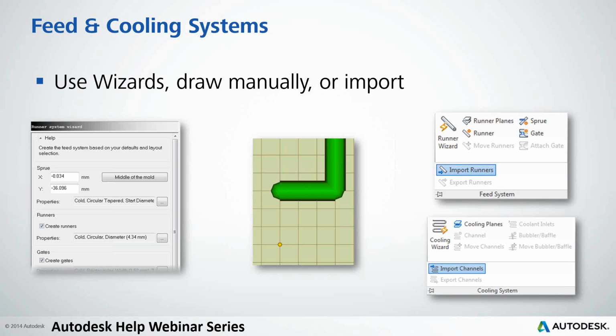And finally, when you're importing the component, either a runner system or a cooling system, you want to look in the ribbon there, and you're going to have to expand it, so click on the words feed system or cooling system, and that'll show the option for importing the runner or importing the channels.